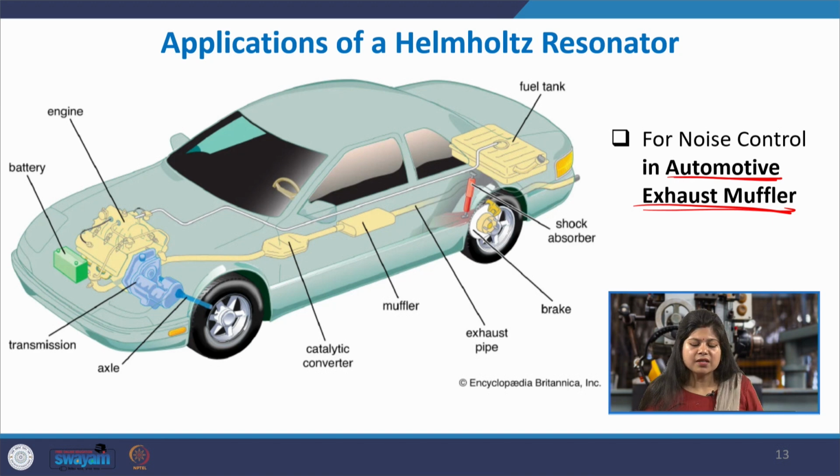These days almost no muffler is built without a Helmholtz resonator. A Helmholtz resonator is there in every modern automotive exhaust muffler, so it is very widely used in this application. What is the purpose? To reduce the exhaust noise.